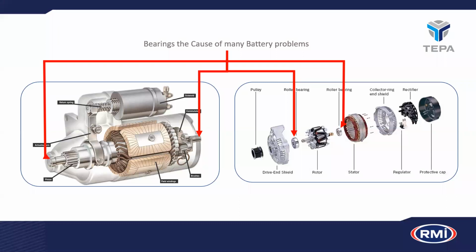When you hear that a vehicle is battling to start and it has a very slow starter that turns over a little bit and then it stops and it chugs and then it will turn over slowly and then suddenly it'll go again, and everybody thinks, oh gosh, the battery's dying, you're probably finding that your starter motor bearings on the front of the commutator and the rear are actually worn out.